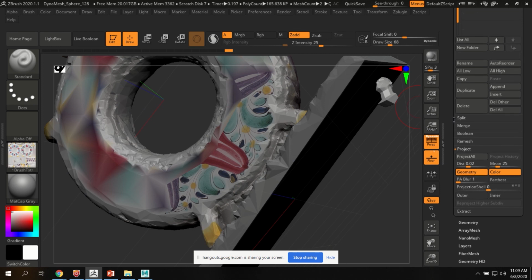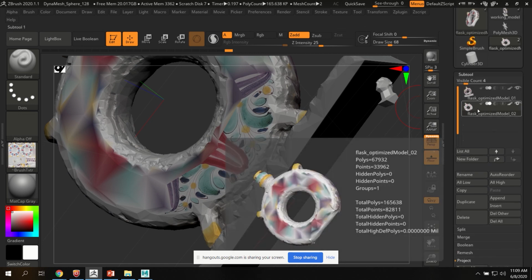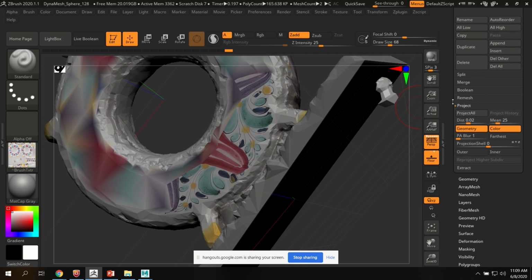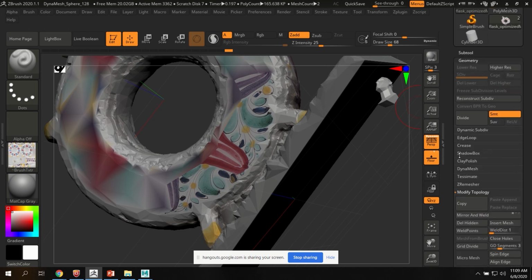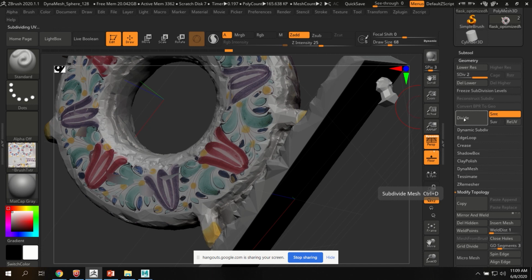If I want my model to have a higher poly count, retaining whatever color information that's not being supported, and you already went a couple steps through and you already decimated it, you could raise the poly count by subdividing it, and you can do that by going to geometry. Right, yeah, default geometry. If I hit divide, I'm going to hide my original model.